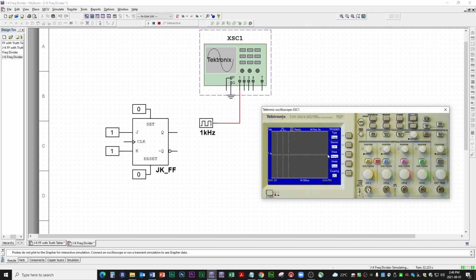And let's see, we can just change the level at which the oscilloscope can actually lock on to that signal. This 0 reference is going to stay, but this is the trigger level. This is when the oscilloscope is recognizing a solid signal. So let's move that a little bit up and see if we can make it stop. All right, look at that. Now the scope can sense the signal and can lock onto it nice and solid. All right, so that's good. So we can see our signal.